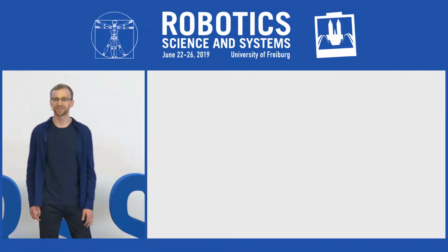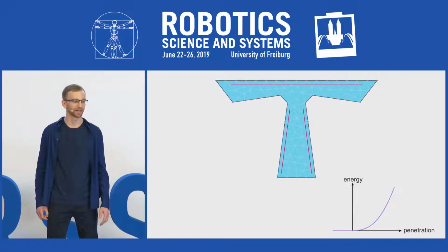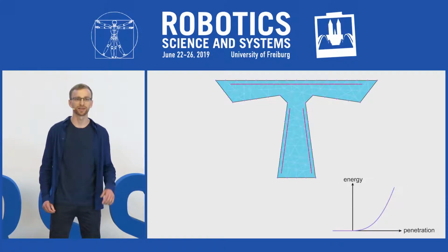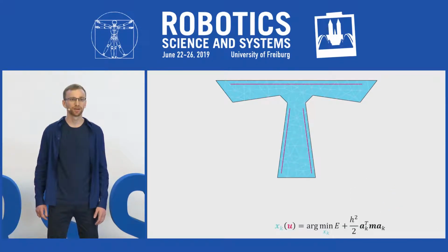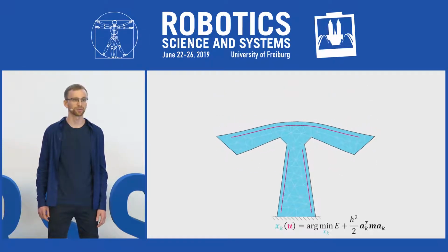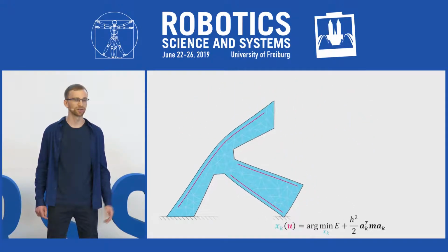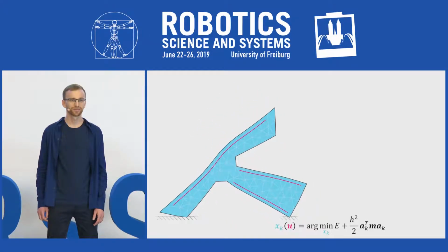Now let's turn our attention to dynamics. So we're going to use a penalty method for contacts, which applies normal force as nodes penetrate the floor and works similarly for friction. We can adapt our minimization from before to integrate forward in time according to implicit Euler, giving us the stable forward dynamic simulation shown here.